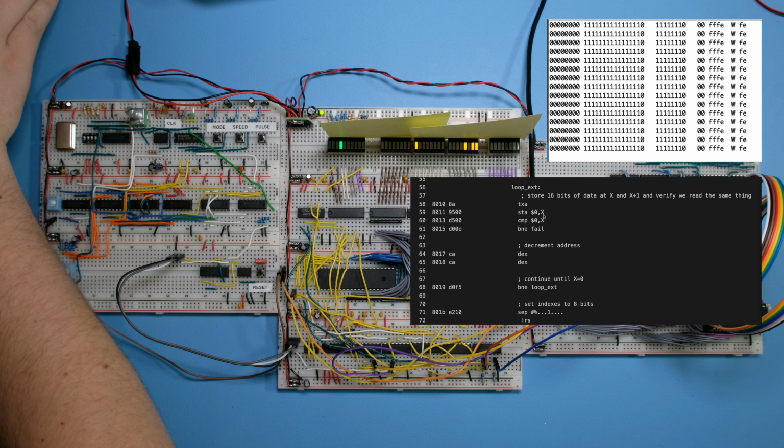And this should generate a bank address. However, as you can see here, the bank address is still 0. So the code is not actually working. It's not generating a bank address. And I'm not sure why, because at the moment this is trying to write in the ROM space. And so, of course, when I try to read back from the ROM, I read EA, which is what the ROM is initialized to. That's normal, but then this makes the program fail.